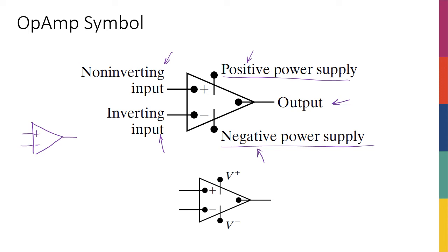So in a few slides, we're going to see why it is important that this voltage at this point is 5 volts, 10 volts, 15 volts. So sometimes that number is important, sometimes it's not. And you're going to see in the examples when it is important and when it's not, right? But generally, you have 5 terminals, so 2 inputs. We have the positive input or non-inverting input, sometimes we show it as P, and then the negative one, so N. We have the positive supply, V plus, and negative supply, V minus, and then we have the output. Okay.